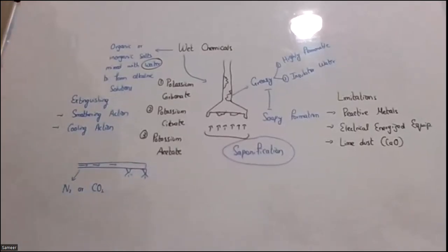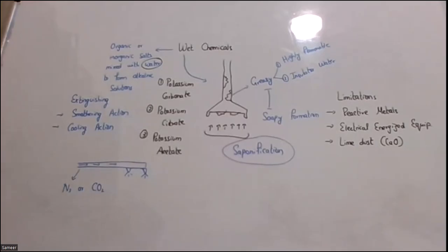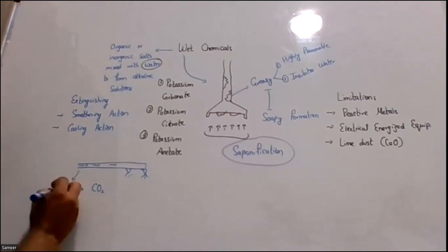These two gases are usually used because they are cold and can easily push the liquid form out of the sprinklers and nozzles. So they can expel wet chemicals from the piping very easily. The gases used for expelling wet chemicals are nitrogen and/or carbon dioxide.